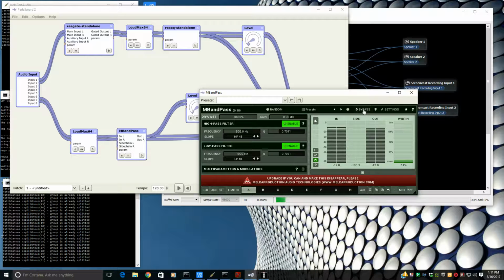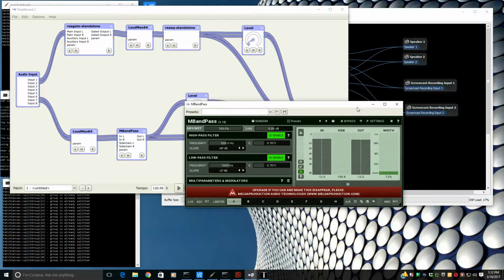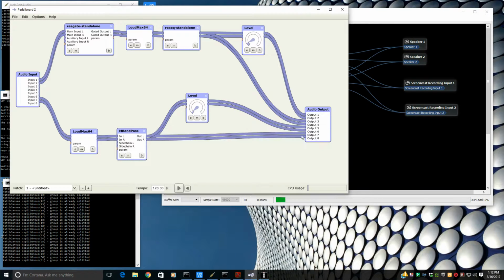So just like a bit of a crystal filter going from 1.2K down to 500 hertz bandwidth. So it cuts out those far-reaching low frequencies and high frequencies. Concentrates more in the middle part, which is where most of the CW tones are located.